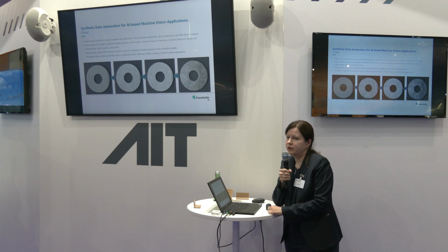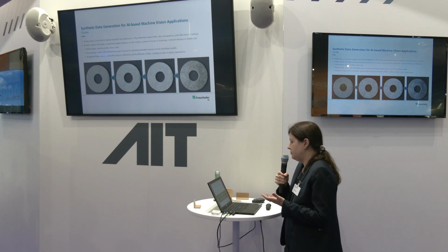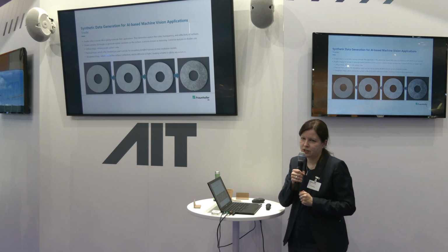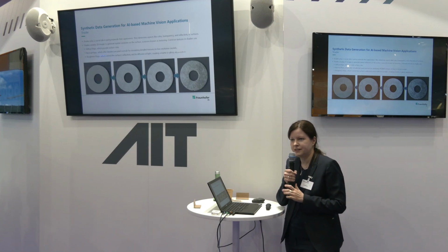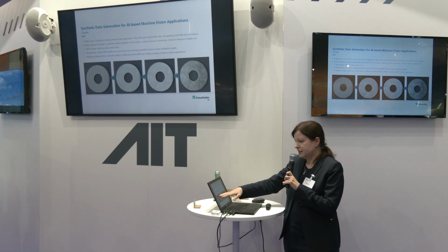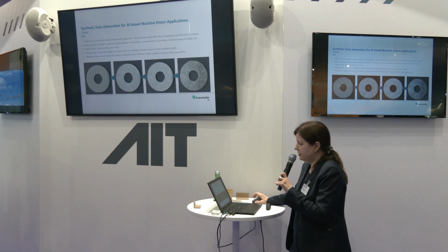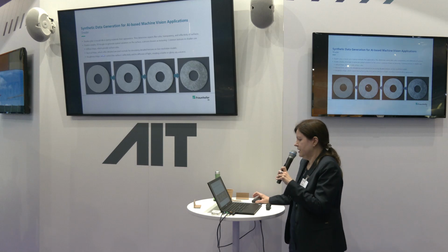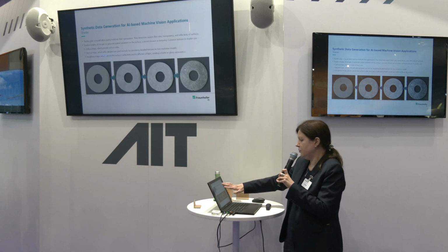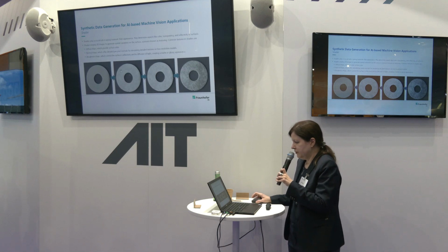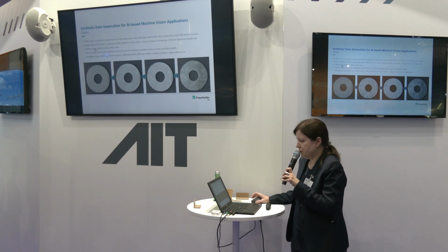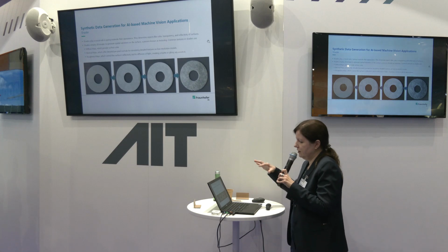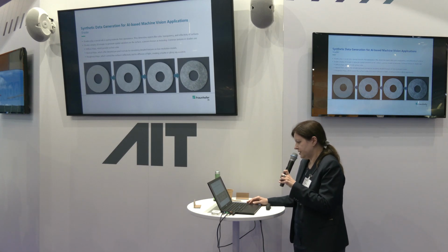Then, of course, what is very important is the material of the object. Depending on which kind of material you have, a completely different surface structure, you have other reflections, things like that. And we start with only the geometry and a basic material, for example, a metal, yes. And then we do the shading, we modify the surface structure with different kinds of maps, diffusion maps, normal maps, roughness maps, to get the final object surface.